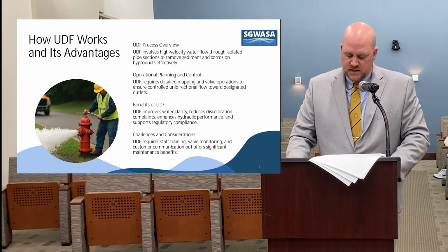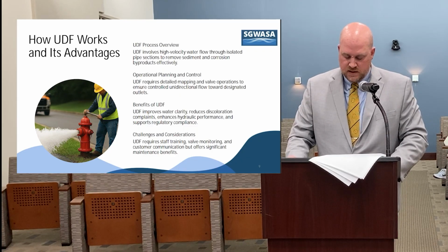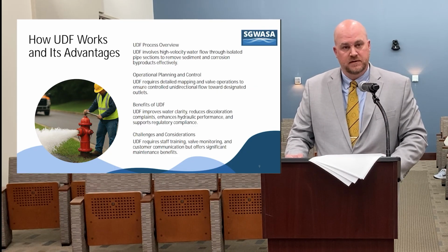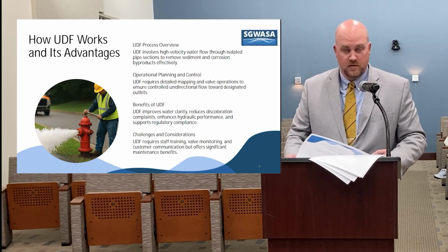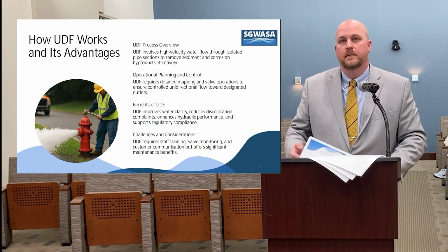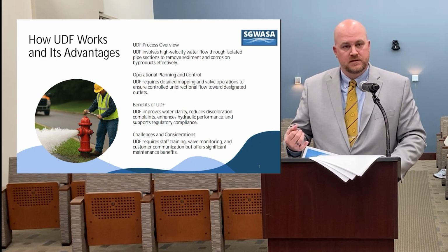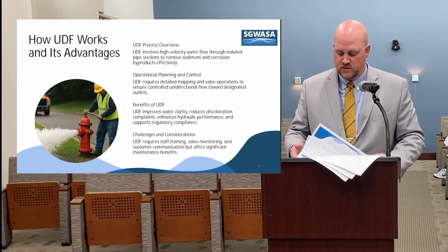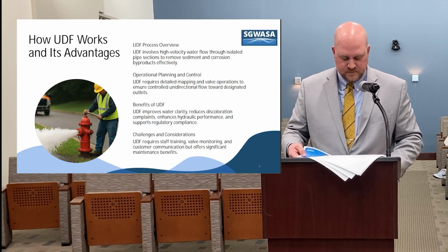There are challenges and considerations though. UDF requires staff training, valve monitoring, and customer communication, but it does offer significant maintenance benefits, which I went through earlier as far as pulling out sediment, also pulling out corrosion in pipes to ensure longer pipe life.